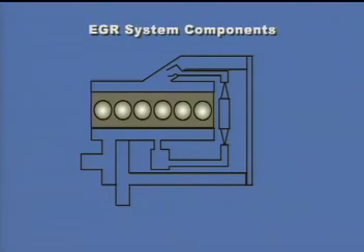Pressure inside the exhaust manifold needs to be increased. This is accomplished through the use of either a variable geometry turbocharger, an exhaust throttle orifice, or other restrictions. Details of their operation will be covered later in this program.